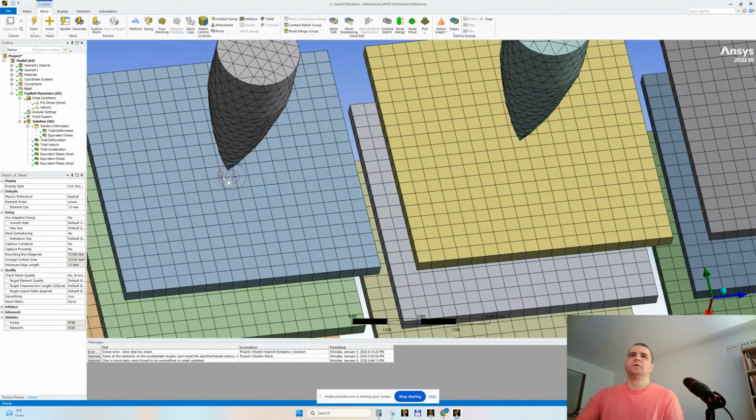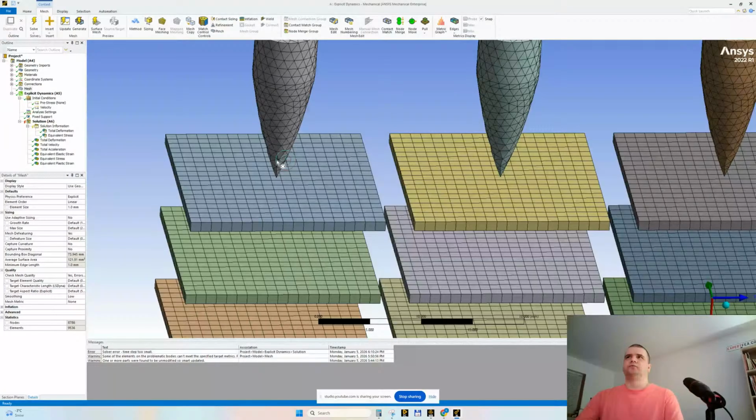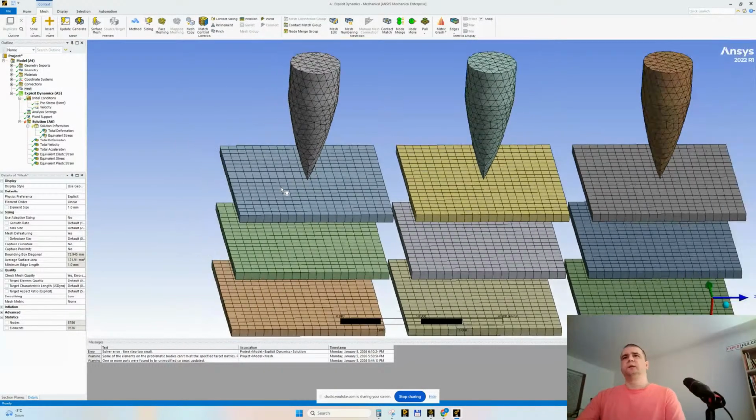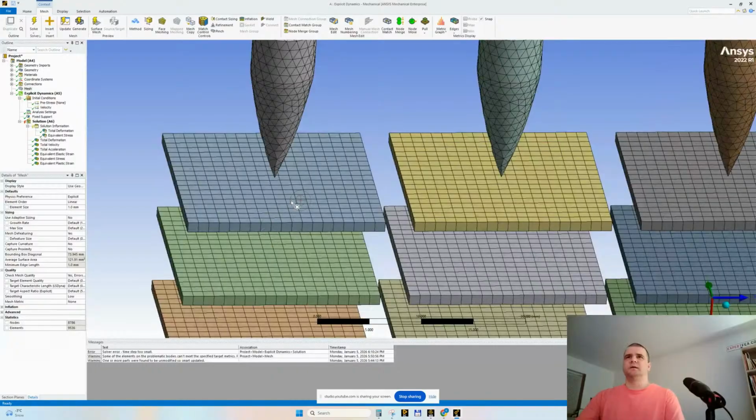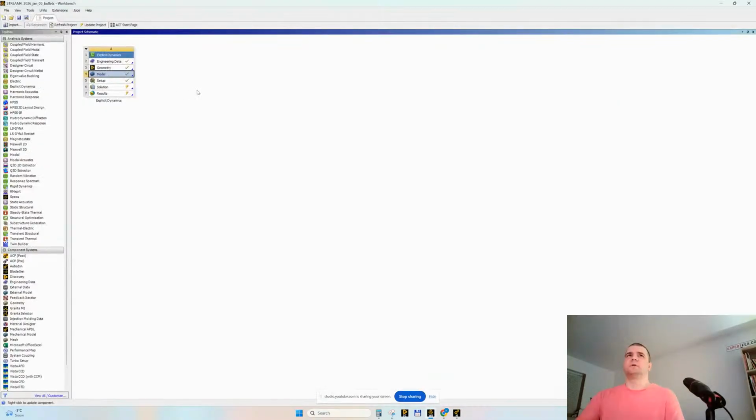For the one who is interested, they should go and check the difference between an element node and integration points. Inside the element, there are integration points. So let's make the plates thinner, and the FEA will be nicer.